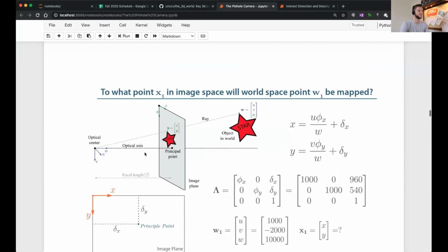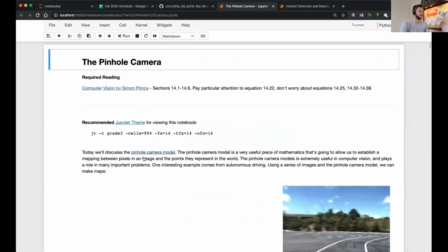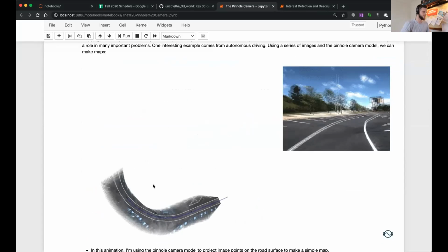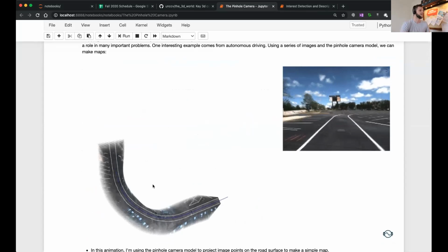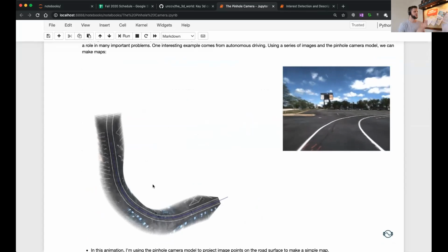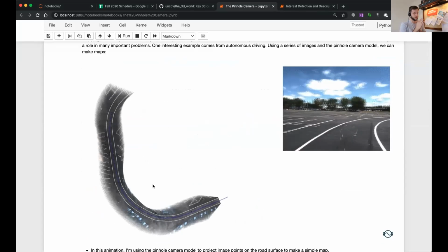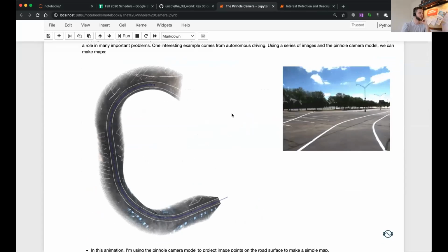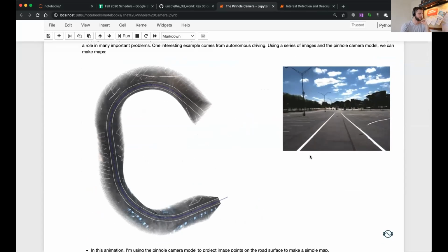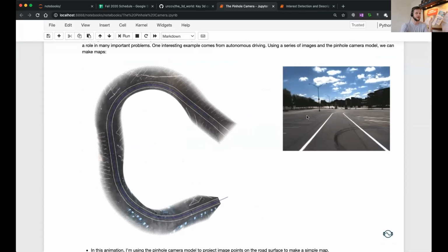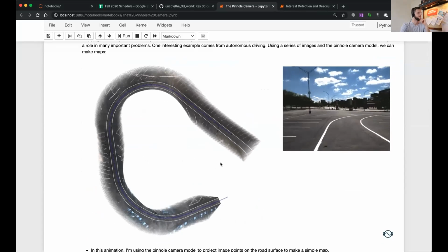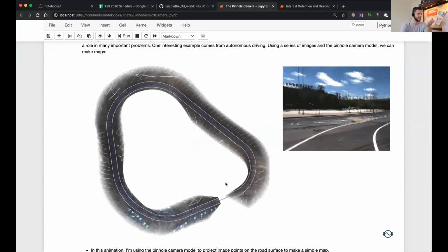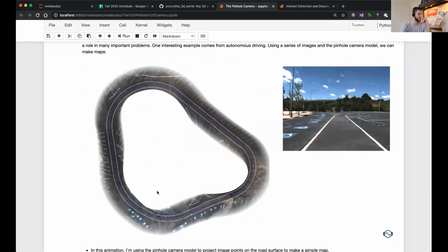Okay. We have been talking about some cool stuff that is related to some of the things Rick has been mentioning, especially the 3D underwater mapping. We've been talking about 3D computer vision: how do you take 2D images and turn them into 3D maps? Last time I shared with you this animation that I made at my last job, where I took a bunch of images and used the IMU in our car to project those images into the world. I used some math that we learned and the IMU data to make this map.